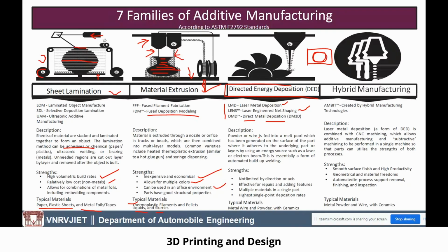And if you want to produce a turbine blade, again we use a platform on which the layer by layer manufacturing takes place. But you can see here a nozzle is there, and the nozzle is connected with the hopper, which consists of 2 or 3 chambers. Let us divide this into 3 chambers. Here the raw material is available in powder form, and there is a heat source, that is a laser beam. Due to gravity or some other source, we deposit the powder particles here, and the laser beam is also coming out.